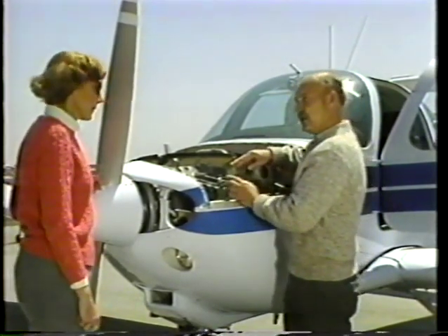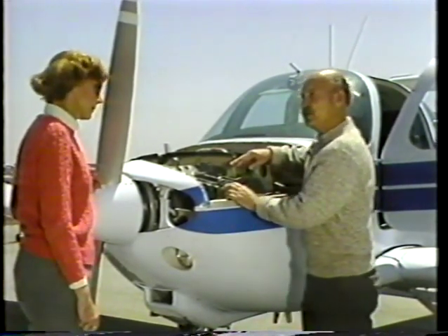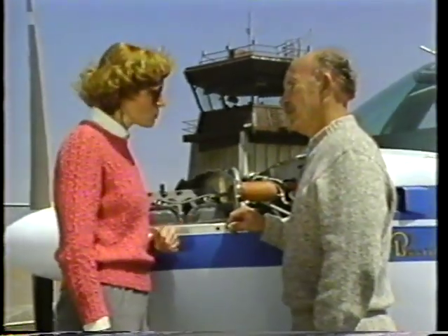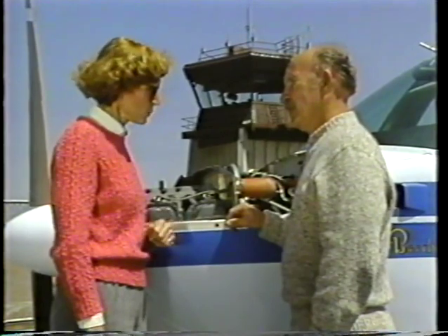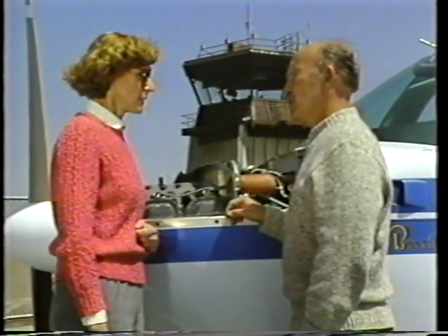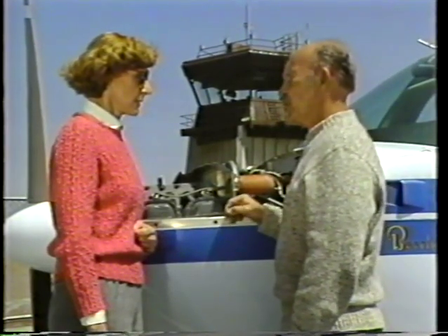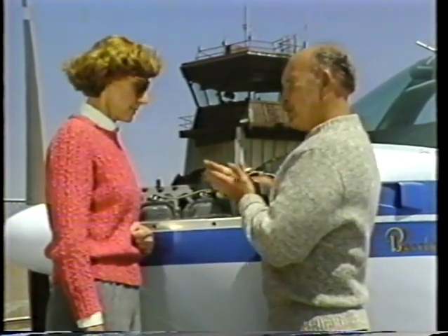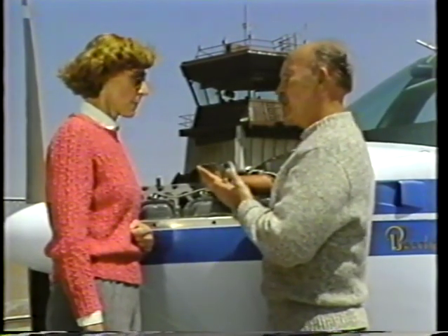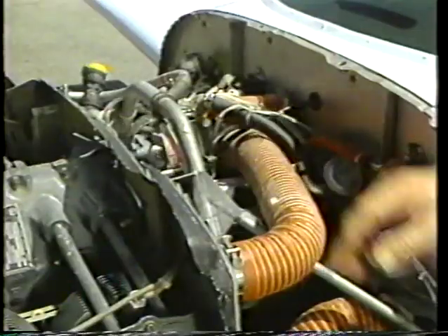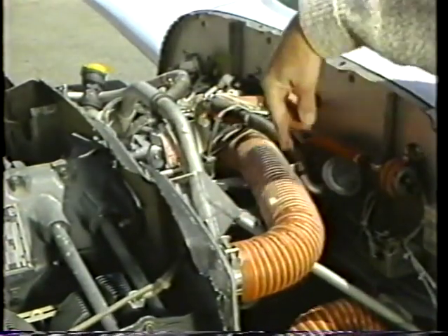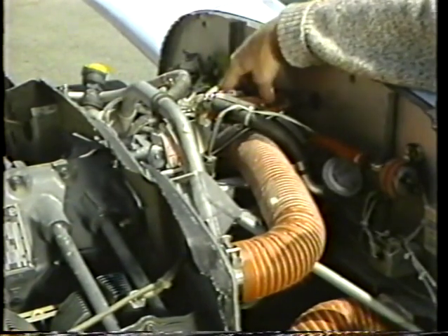A great deal of the heat can also be carried away by the oil system. Ken, you mentioned how the oil helps to cool the engine. Can you tell us a little more about that and the importance of the lubricating system? Yes, Jeannie, the major function of the oil is, of course, lubrication. The oil is circulated through the engine under pressure, and this helps to prevent metal-to-metal contact of the moving parts. The oil carries away a lot of heat during this process, too. The oil cooling air comes in here, travels through this duct down to the oil cooler, where it picks up the heat from the oil and then goes overboard.